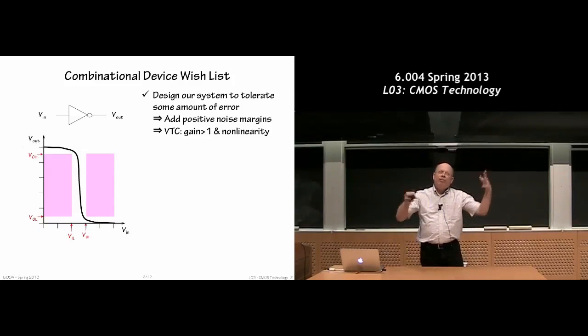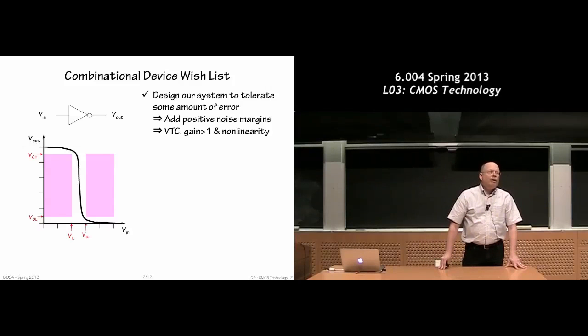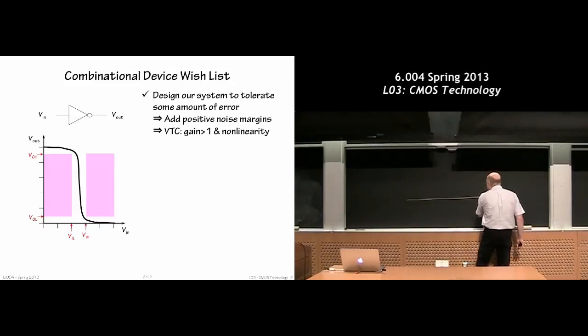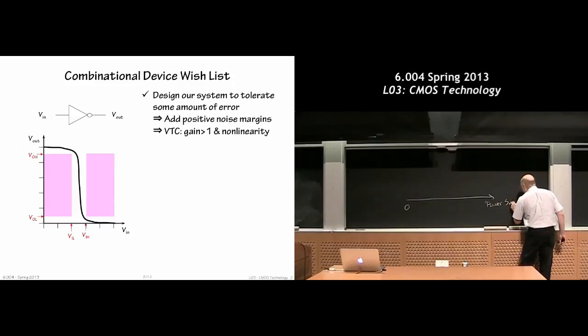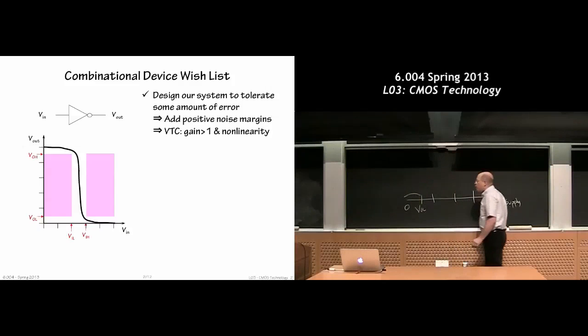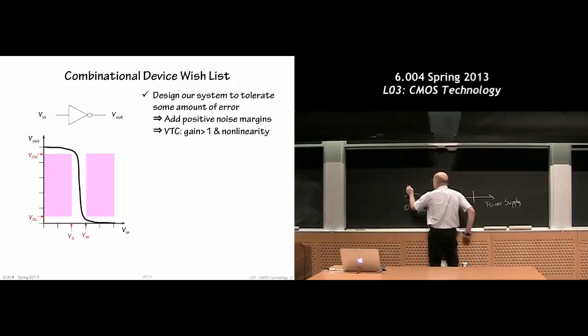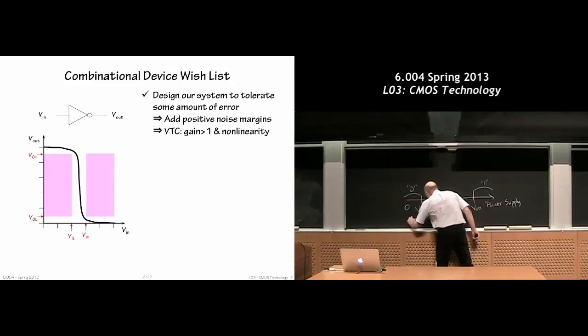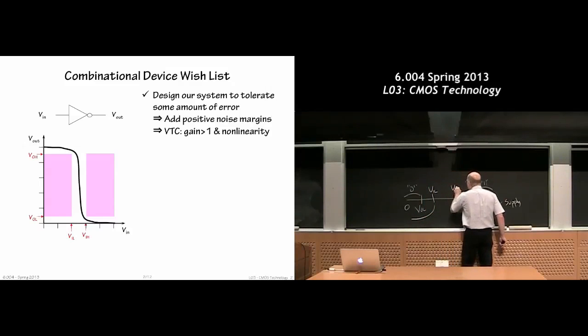So this sort of tinker-toy construction principle was possible, and it was made possible through the use of this digital signaling, where we described using the standard range of voltages that went from 0 up to some power supply voltage at this end. And we divided that up into a couple different regions. So we have these 4 voltage specifications. Any legal device, if it wants to output a logic 0, has to output a voltage less than VOL. If it wants to output a logic 1, this is on the output side, it has to output a voltage greater than VOH. And then on the input side, we had a different specification involving VIL and VIH.